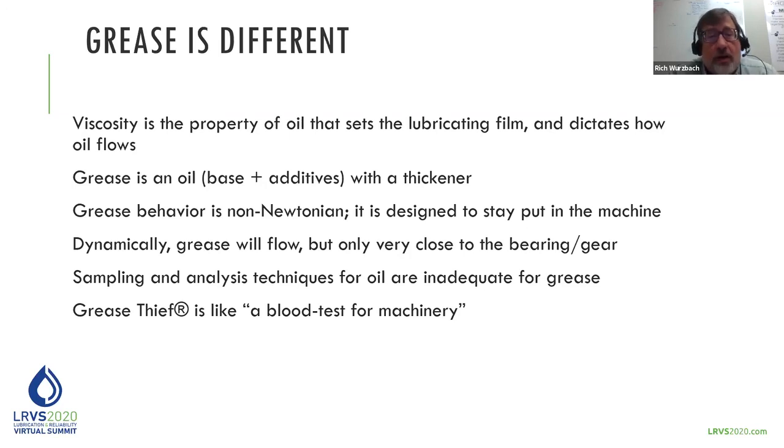For Newtonian fluids, the viscosity is independent of the shear rate, but grease definitely is not. We can see grease behavior change as we change the shear rate. And the rate at which the grease starts to behave in a more fluid manner rather than a solid or semi-solid varies with temperature as well. So dynamically, within a machine, we may have a situation that allows grease to flow, but maybe only very close to the bearing or gear or whatever's moving inside that machine.